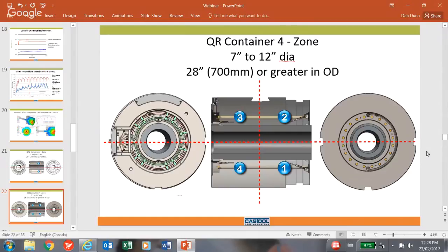The container, once preheated, will have a Castool specified set of parameters, which is critical to its function. There will be an effective taper front to back. Second to this, there will be an offset top to bottom on the die side of this container. The offset will be based on the zone 2 top side of the container. Whatever the temperature reading is in this zone, a predetermined offset will be added to zone 1 or the bottom of the die, to compensate for any heat loss due to the die slide, auxiliary tooling, and the plain thermal dynamics of the press.